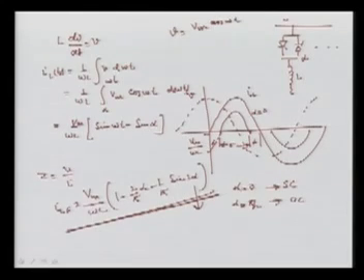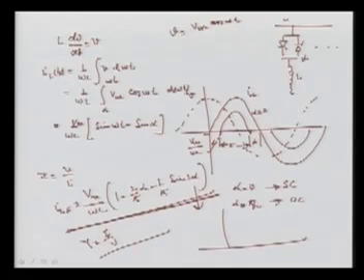So again the admittance Y is I upon V, and then we can get the expression here. Now you can see how this ILF, the fundamental component of the inductor current, changes with alpha. Harmonics, let's suppose, we are ignoring. So you can see it starts from a higher value when alpha is 0, and then at pi by 2 it is 0, and this is the value.